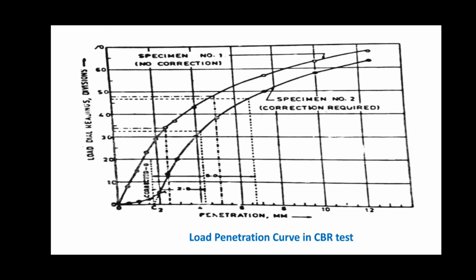The average CBR value of the three test specimens is reported to the first decimal place as the CBR value of the material, and if the variation in the CBR value between the three specimens is more than the prescribed limit, then the test should be repeated on an additional three samples, and the average CBR value of the 6 specimens should be accepted.